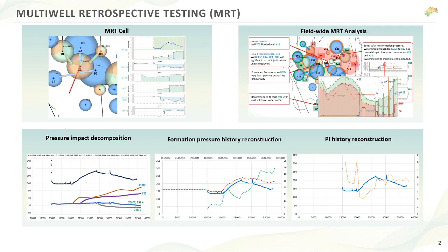So a transient response could be a drawdown transient response, which is a response in the well itself. So which pressure will I have if I produce in my well with just 1 barrel per day. And another class of transient responses are cross-well transient responses. So what pressure response will I have in the offset well if in my well I will start to produce again with 1 barrel per day? Right. So this set of mathematical functions will give me a model of a whole block of interfering wells.